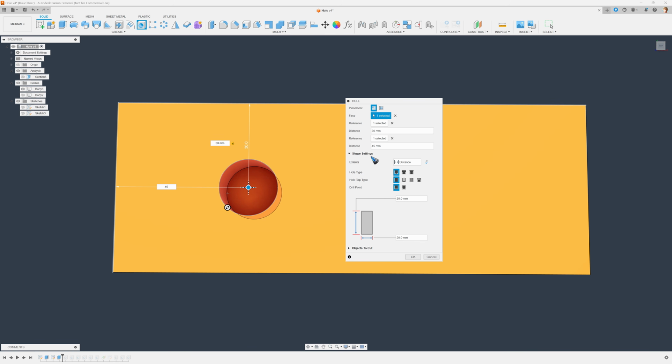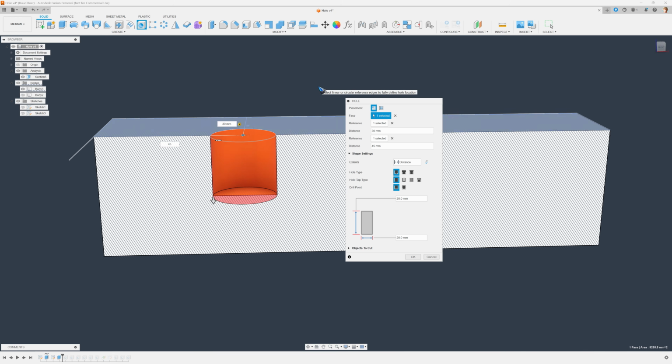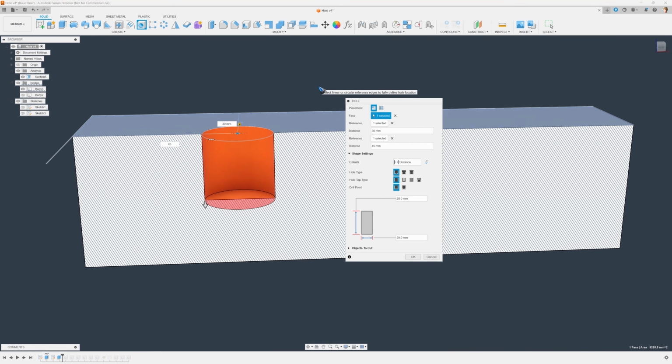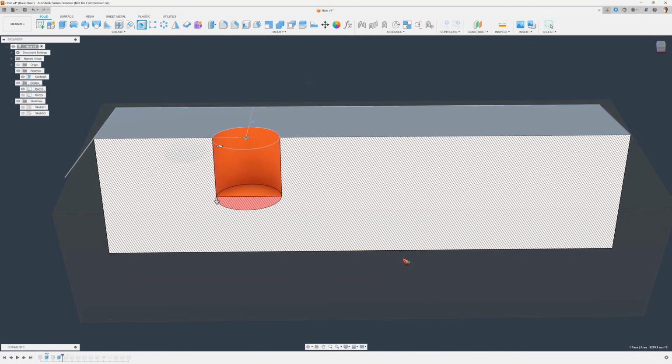Then we can select a shape. The hole type is a normal hole, that is what an extrude would do. Which means we don't tap any thread inside, and we also have a flat bottom. And now if I open up a section analysis, we can see that we get a normal straightforward hole that we would also have got with an extrude command.